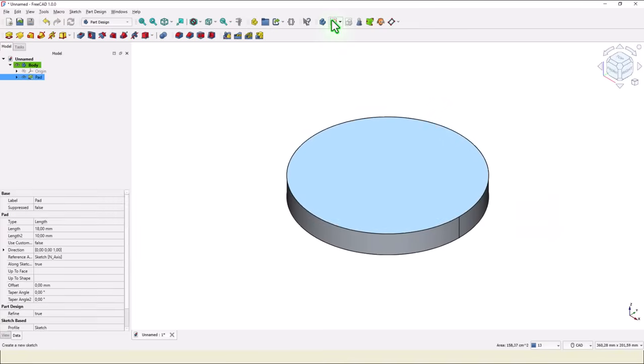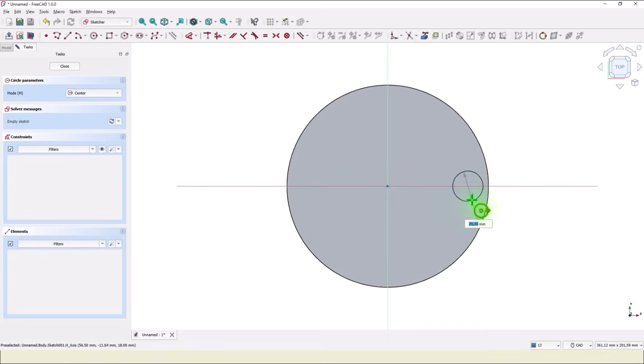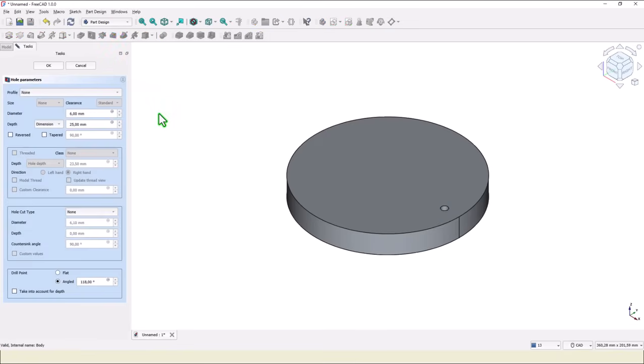This face for a new sketch, circle placed on this axis, no important dimension of the circle because we use hole tool. As I said, 11 is the diameter through all, then counterbore 18 and 11.